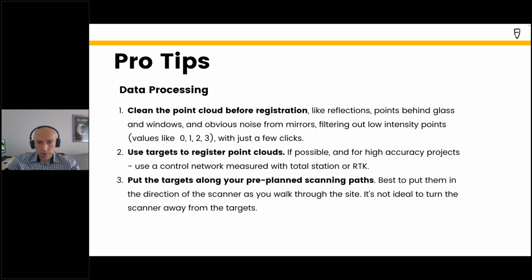I have already talked about this. Use targets for registration of individual scans and use a control network for high accuracy scans, for a high accuracy project. It is very important to spread your targets evenly on your object, like on the perimeter of your object.